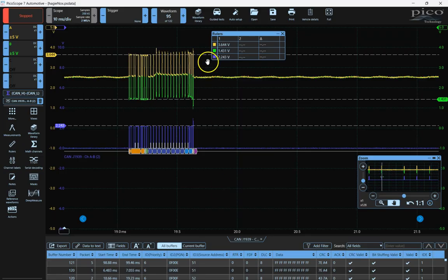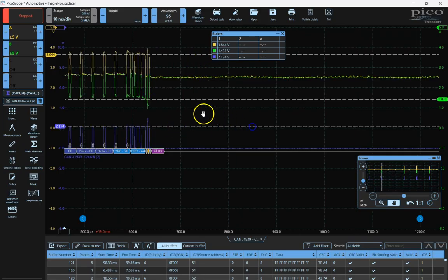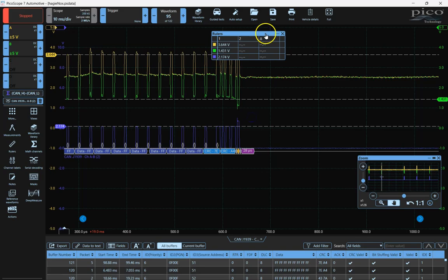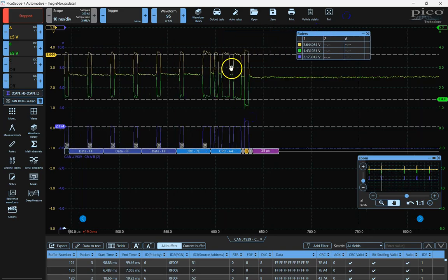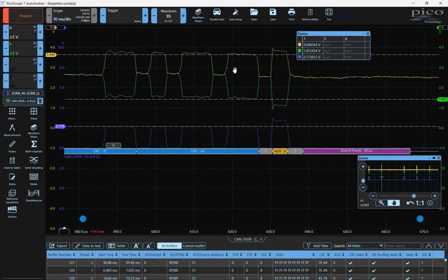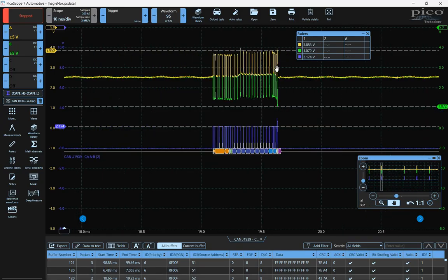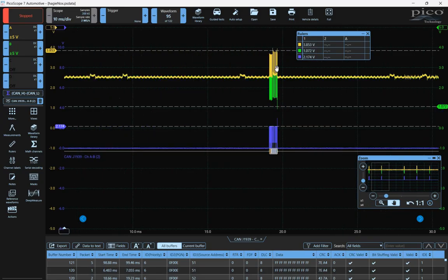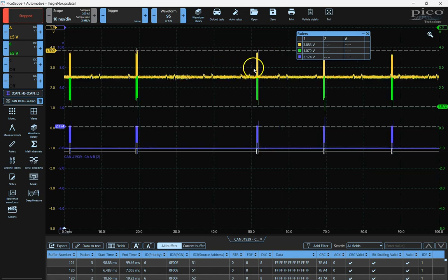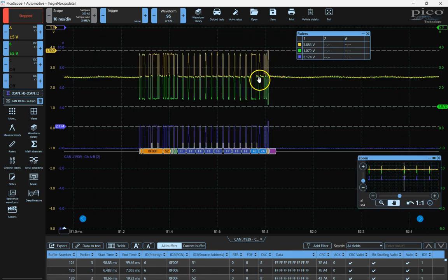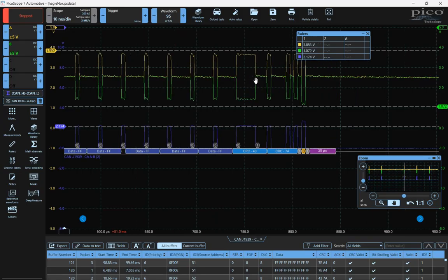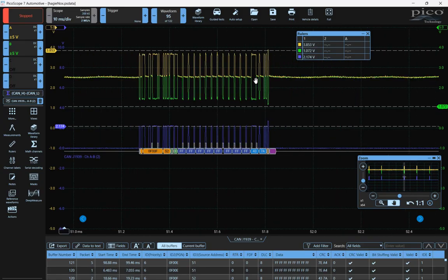And we can see, as I indicated before, our acknowledge bit. On real machines, on real equipment, we've got more than one controller here, so my acknowledge bit has a higher amplitude than any of the others. As I said before, I've had techs tell me, well, there's a spike at the end of the data. Well, this kind of looks like a spike when I move this out, and you think, oh, there must be some noise there. This is just the acknowledge bit. This is how this works. This is how this functions.